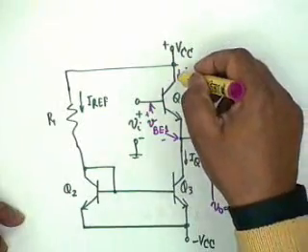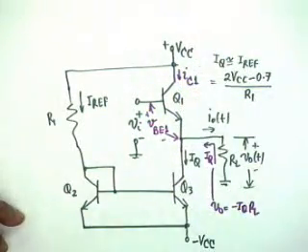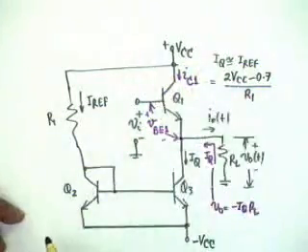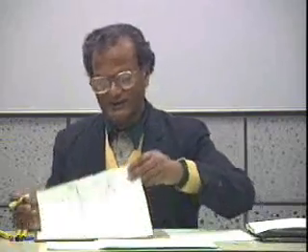In other words, nothing flows through Q1. So, Q1 goes into cutoff, not saturation. Saturation, it flows a current. But if it does not give a current, if it doesn't contribute to a current at this junction, it means it's cut off. So, physically, much before this inequality starts affecting this circuit, Q1 shall be cut off, which means that